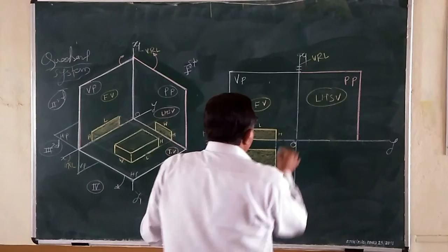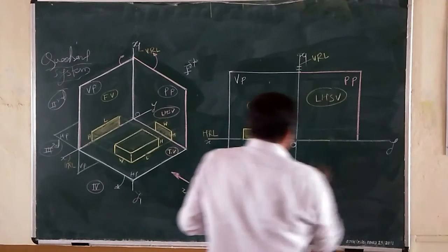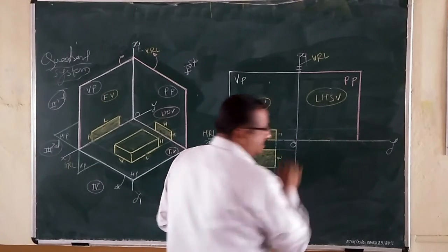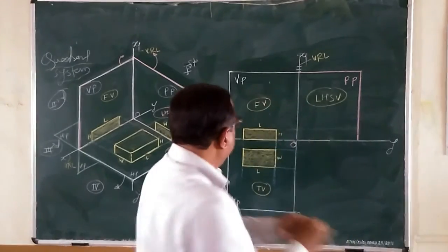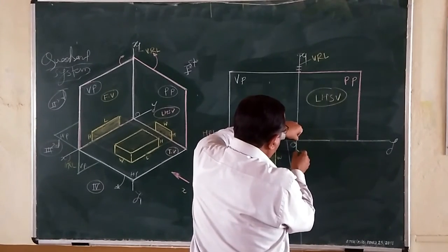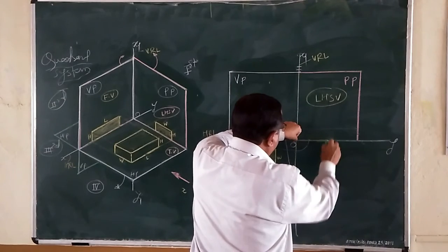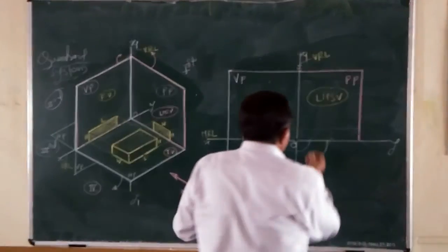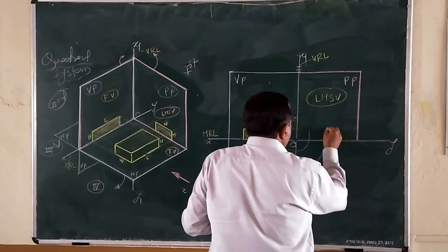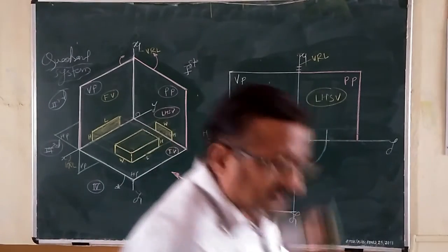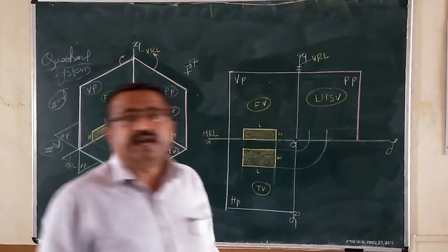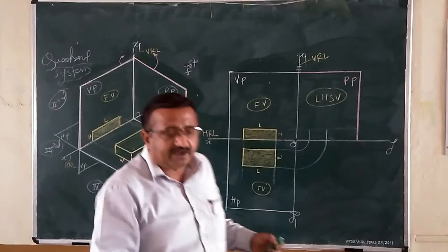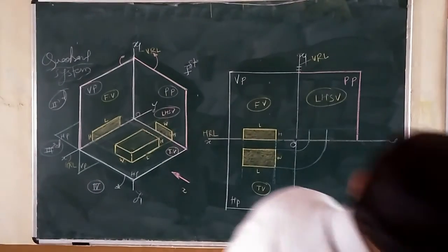Now what you have to do is project this height in this way on the right side. Okay. Similarly, width up to here, place the projectors, and by compass only tilt those horizontal projectors by 90 degrees from here up to HR in this way. From here up to HR. Now extend those projectors up. Over. So magically on its own, the side image is getting created. No need to use any kind of scale. Scale is not at all required. Only cross projectors will define or yield us the desired shape and size of the side image.